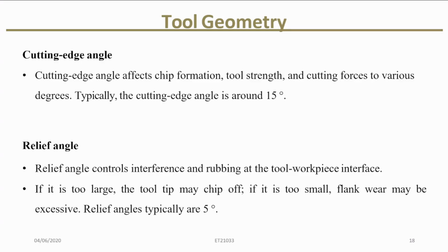And the relief angle. Relief angle controls interference and rubbing at the tool workpiece interface. If it is too large, the tool tip may chip off. If it is too small, flank wear may be excessive. Relief angles typically are 5 degrees.